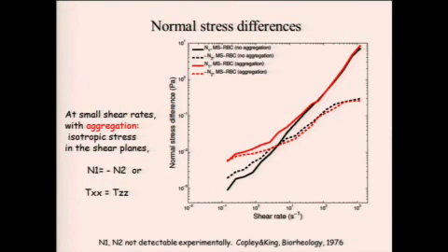When we measure the shear stress from which we derive the viscosity, we can also measure the normal stresses. The only interesting thing about the normal stresses, I think, is that they've never been measured because it's too difficult. Blood has too low a viscosity, so when you put it into one of those rotational instruments that are used to measure normal stresses, you simply measure inertia effects.